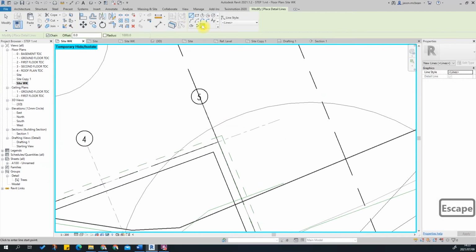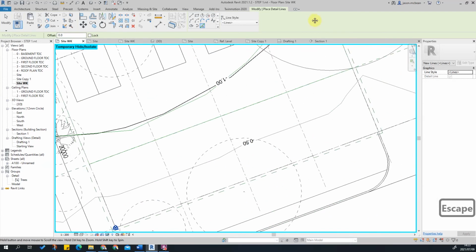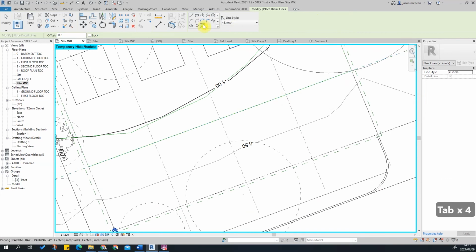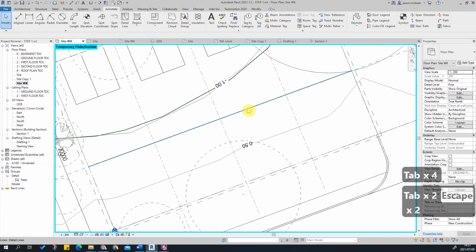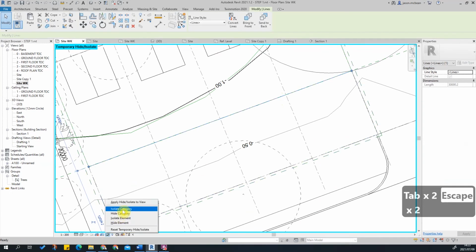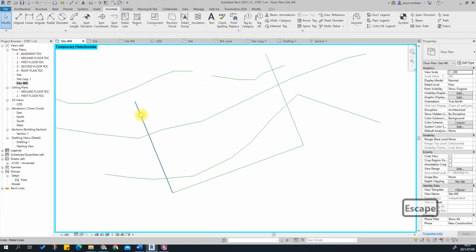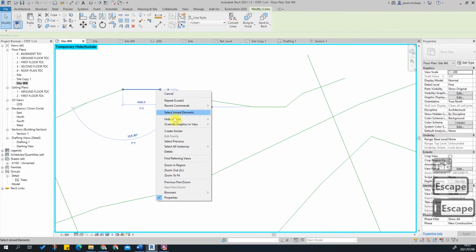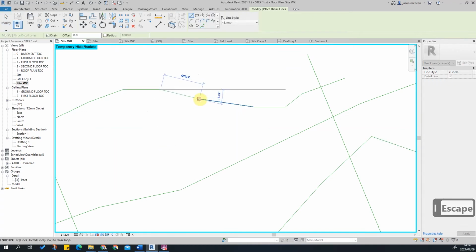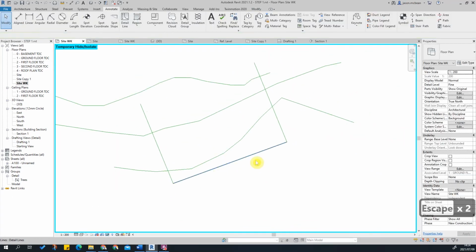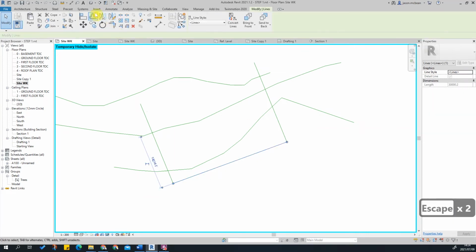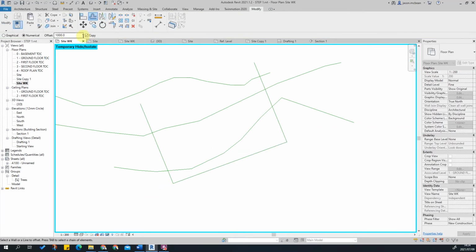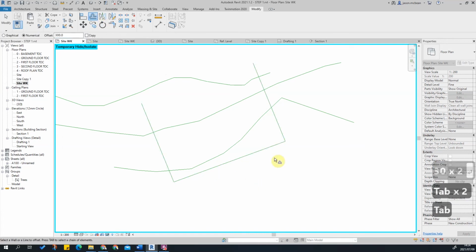Now I'm going to offset that line work. So pick that green line. Pick line tool. Okay, I just want to select your isolate category. And I'm going to simply say, select all of this. Okay, that should have been closed as well. Line, create similar. Select this bit of line work, and I'm going to use this offset command. Offset command, switch off copy, and I'm going to just make this 300 because it'll be a 300 concrete wall maybe. Click offset again, tab. So I've just offset everything in 300.